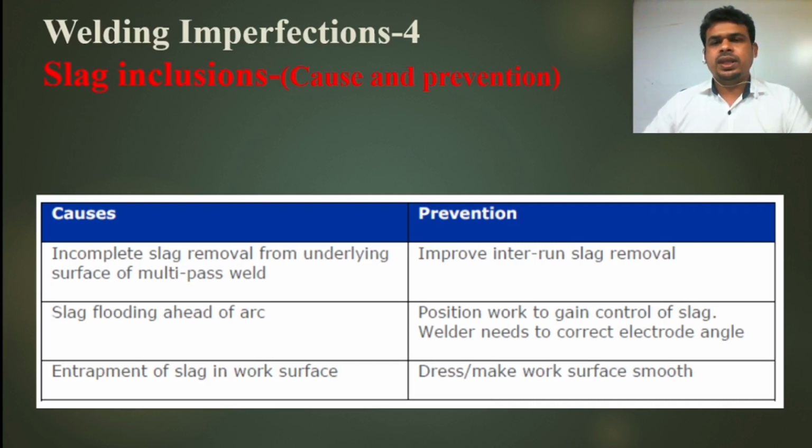Then the prevention: improve inter-run slag removal. When we do multi-run process welding, before doing the second pass or third pass, we need to remove the slag and all the rust properly, and only then can we go to the next run of welding.